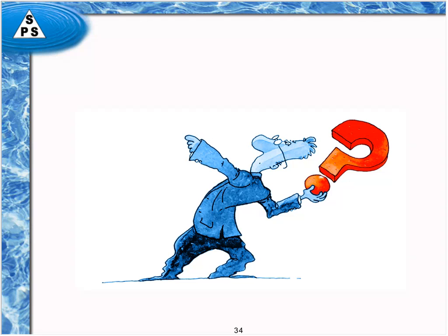If you have lots of cracks and crevices in your system and you cannot use heat, then you are probably going to have to disassemble some things in order to hand sanitize some pieces and parts that it would otherwise never get to. So there are some issues associated with removing biofilm that are very challenging because it can get everywhere, especially if you've given it enough chance to get everywhere by not sanitizing very often.